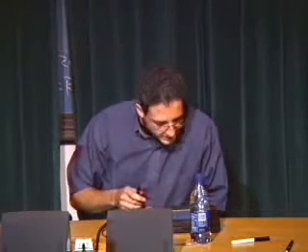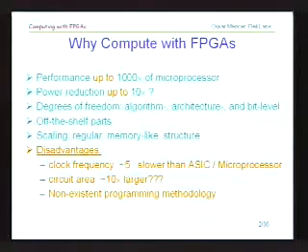So if we look at the disadvantages further, we also have many years of compiler development for microprocessors and programming methodologies and ways of actually dealing with these devices, whereas FPGAs really are just targeted at this point by synthesis tools that are coming from a different field, from implementing chips, and just applied to FPGAs and you get the circuit in there. It's really not a programming environment. What you have is a design environment that will get you a circuit that works perfectly, but it will take you a long time to get there.